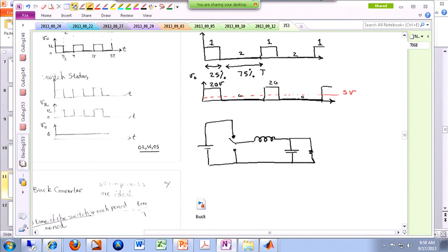and what they do is they take the input voltage, which is kind of this square-shaped voltage, and then they only deliver you the DC component of this, and eliminate all the harmonics. And so we have an L, we have a C, this is our load, and this was the 20 volt of the source. So there you go, you have a buck converter. All you have to do is realize the switch using the semiconductor devices that we have.